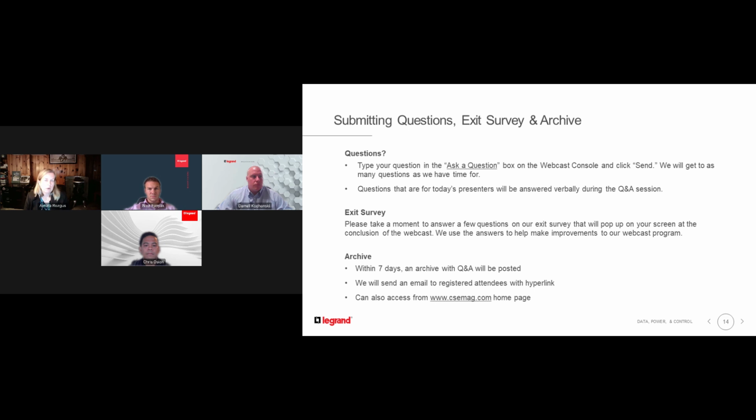All right, Chris, you're already talking, so let me ask you another question here. Is there a specific requirement for areas with a higher earthquake possibility? So what are the seismic requirements here? Yeah, we have a standard offering and we have a seismic offering as well. We've shake tabled the busway to meet IEEE 693, and we also have OSHPD available as well. So if you're in a seismic zone, we do have product available to help satisfy those requirements. So yes, the answer to the question is yes, Samara, we have that available.